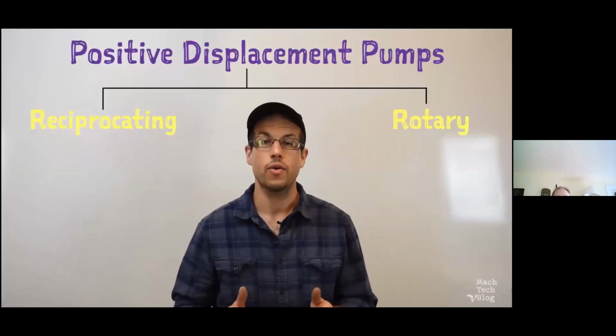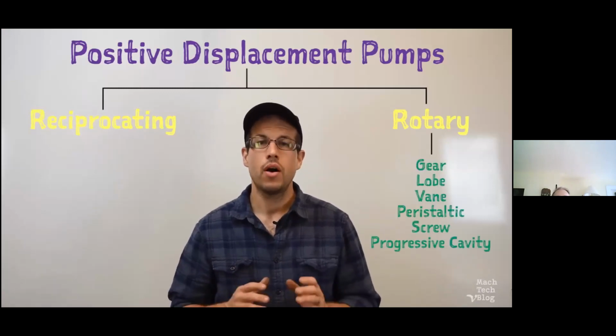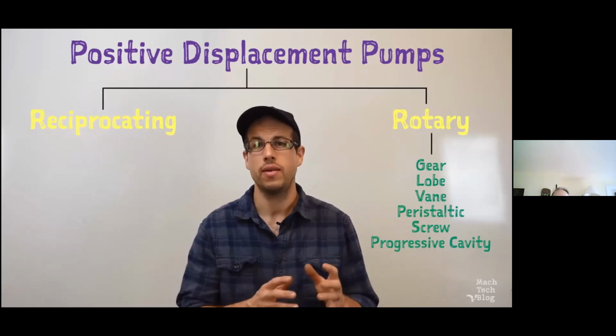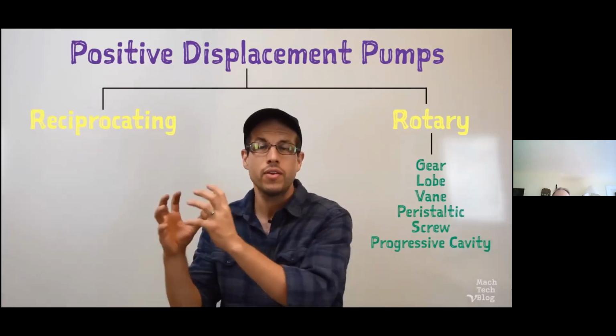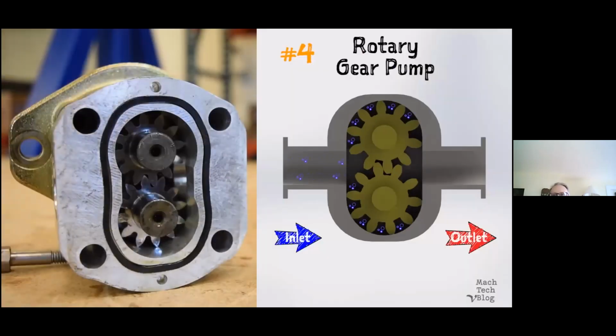The second category of positive displacement pump is the rotary pump. All rotary pumps utilize some kind of a moving chamber that traps fluid and carries it from one side of the pump to the other side. To illustrate this concept, let's look at pump number 4, the gear pump.